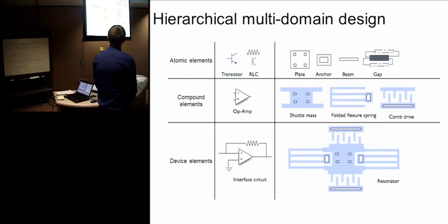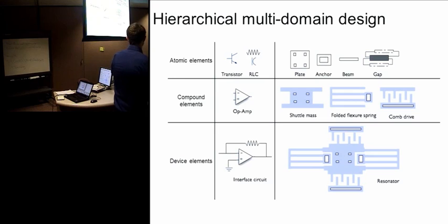These are just some examples of some elements that you would find in the Simple library. So anything from the small elements, the atomic ones, then more compound elements, and then device elements like this Resonator here. When you double click each element, you'll see a list of values that you can change. We include an element guide which has every single Simple element in it and then explains what each value is and why you would want to change it, common applications for certain elements.